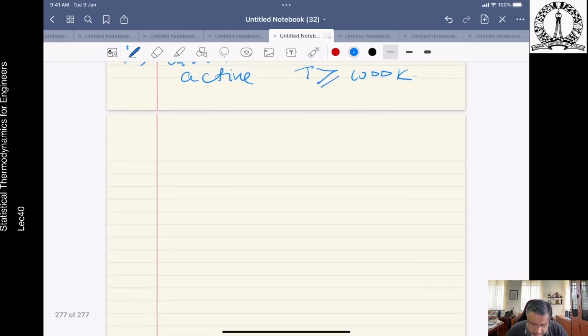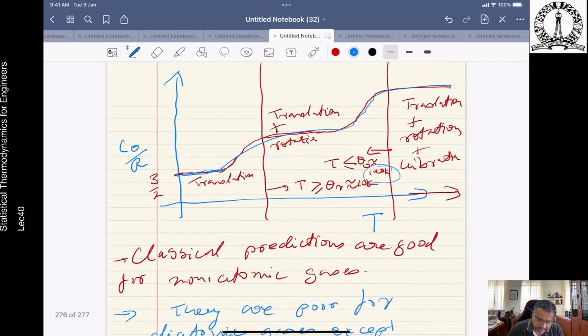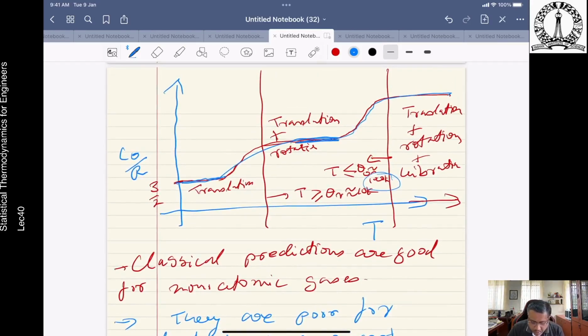Okay, so that is the basis. The influence of temperature on the specific heat follows this kind of behavior. The plateaus that we see signal full excitation of an energy mode. So here where it plateaus, that means all the translational and the rotational modes are fully activated. Here it means all the translational modes are activated.